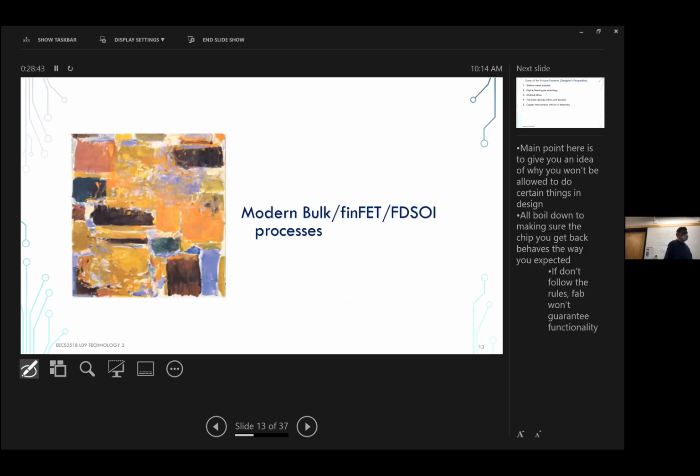Okay, so that's it for lithography and implications on the design. The idea of all what I've been talking about so far was to get you to make sense of design rules. Whenever you're designing something, we are talking mostly hypothetical, but you may want to flip through these slides once when you encounter these design rules and say, oh, yeah, that's what it is. That's what the coloring error is. When our students encountered them in a 28 nanometer process, they were very frustrated with those.